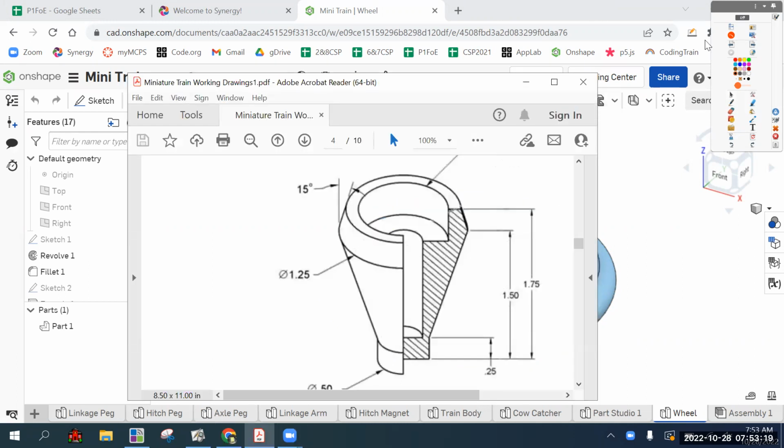So there's two ways to do this smokestack. The clear, obvious one is some sort of revolve, because they've given us a section view, like an inside view, where the vertical line would be our revolve axis. So we would just need to draw this sketch and then revolve it, which you could do as it's shown by trying to figure out what these lines are.